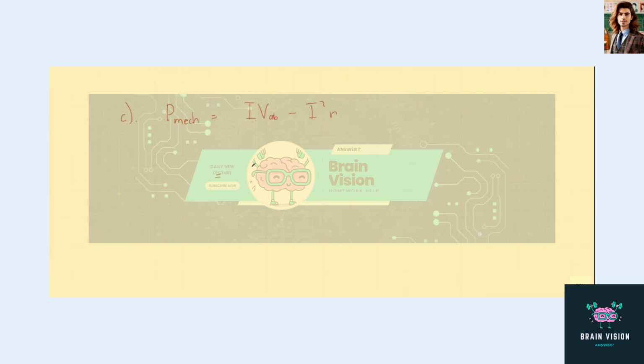And so this is equal to 564 watts as calculated above, minus 4.7 amperes squared times the internal resistance of 3.2 ohms. And so calculating, we get the power developed by the motor to be 493 watts.